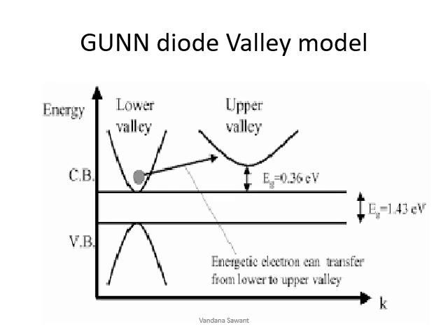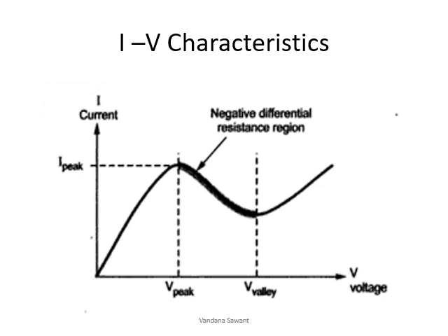As the group or bunch is formed, you know that the mobility goes on decreasing. As the mobility decreases, the conductivity decreases, and as the conductivity decreases, the output current decreases. So the device starts giving a decrease in current. If you plot the current-voltage characteristics for this device, it will look like this. Initially, if we increase the voltage, the current goes on increasing, and if we keep on increasing the voltage, due to the forming of the bunch of electrons, the current goes on decreasing.